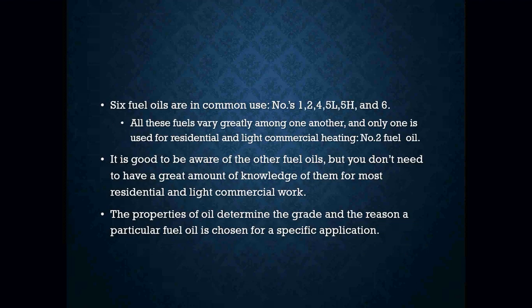We have roughly 6 different types of fuel oils that are in use. You have your number 1, number 2, number 4, 5L, 5H, and number 6. All of these fuels vary greatly among one another, and only one is used in residential and light commercial heating oil, and that is number 2.